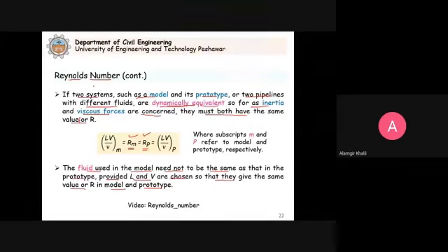Because if the Reynolds number is important, you need to consider it for interpreting or transferring the results, and if instead you consider the Froude number, which is also a dimensionless number, and just say, okay, I only need to consider gravity forces, then the results will not be accurate. So this is important. This comes from basic understanding. If you do not have the basic understanding, then this concept is not that straightforward. Clear? Let us see a small video here.